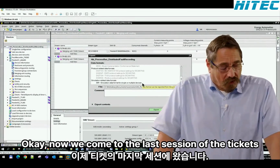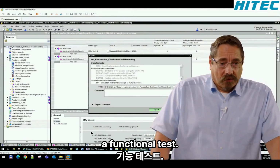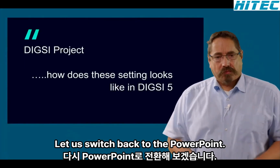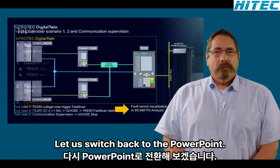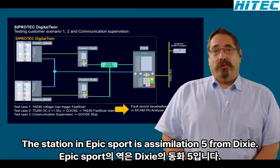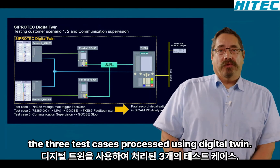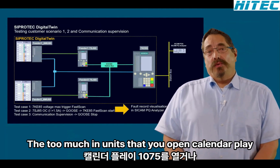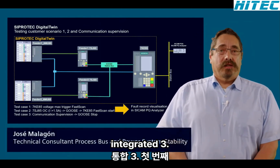Okay, now we come to the last session of the practical, the functional test. Let us switch back to the PowerPoint. As we have now finalized the parameterization and have exported the simulation file from DIGSI, I would like to show you the 3 test cases processed using the digital twin. The 2 merging units, the 2 overcurrent relays, as well as the 7KE85 are simulated in the digital twin.